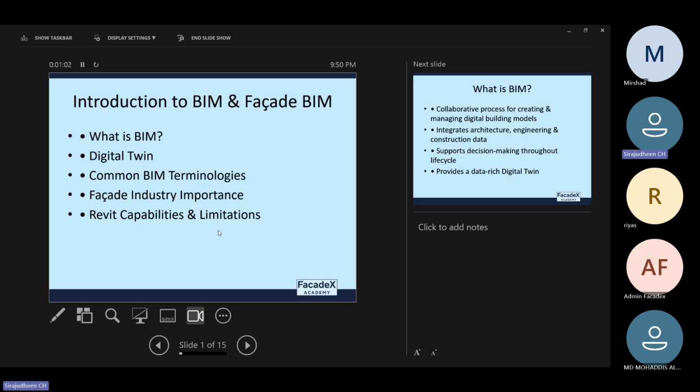So while we are doing this kind of animation, not actually animation, we call it simulation. For this simulation, we can see what element comes first and what comes next. So we can understand if there are any access issues to the existing element, so that we can change our details, or we can change the actual project plan. So BIM helps us in that way also, with this kind of access conflicts and everything.